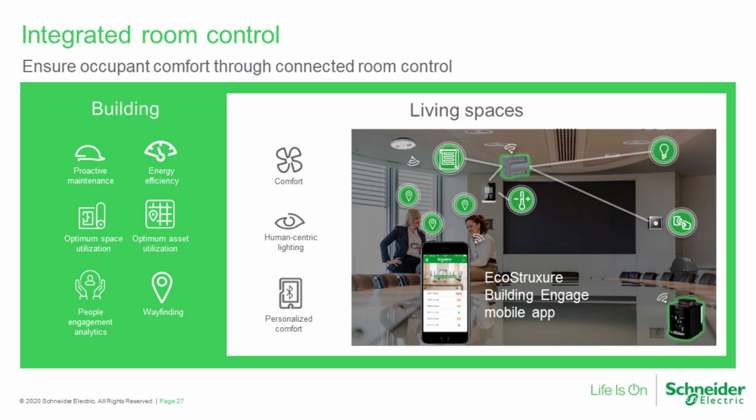And what we're seeing now is a convergence of all these systems, not just because there are savings in such convergence, but because of the benefits we get when we start combining these things, particularly HVAC, lighting, and blind control. All of these really need to start working in conjunction. There is no reason why the light should be on if the room is not occupied, and the room should be set in setback on the HVAC side if it's not occupied. And if it's unoccupied during the day, and let's say it's hot outside and we're not exactly at set point, well, let's raise the blinds and push the setback in the room back and let the sun heat the room instead of us.